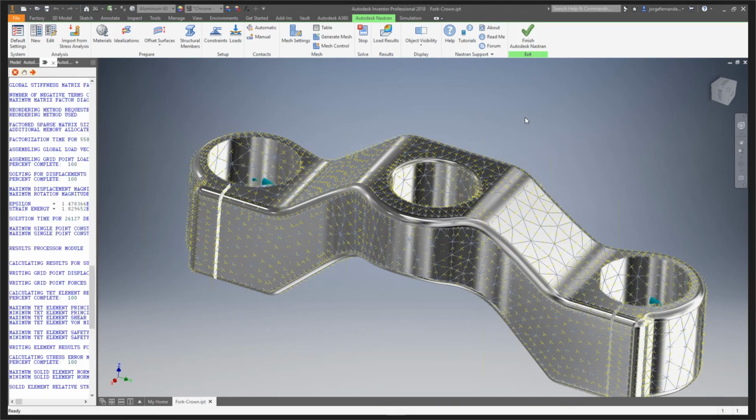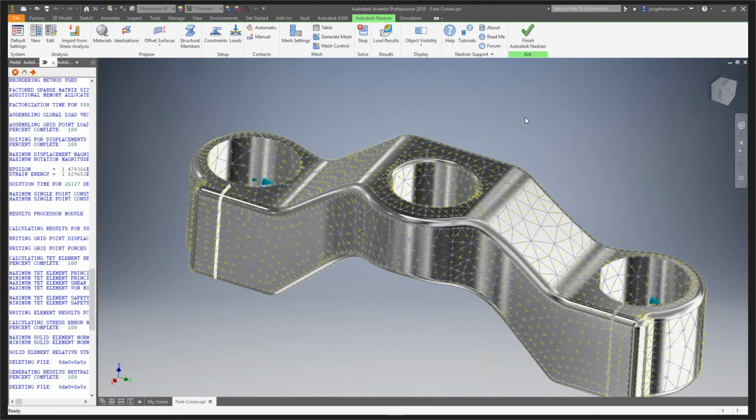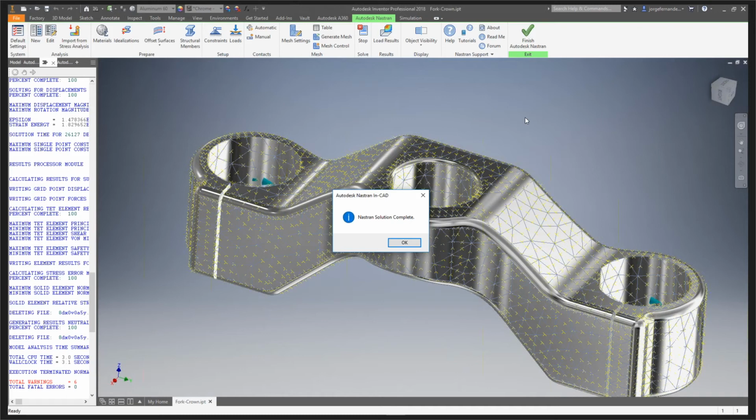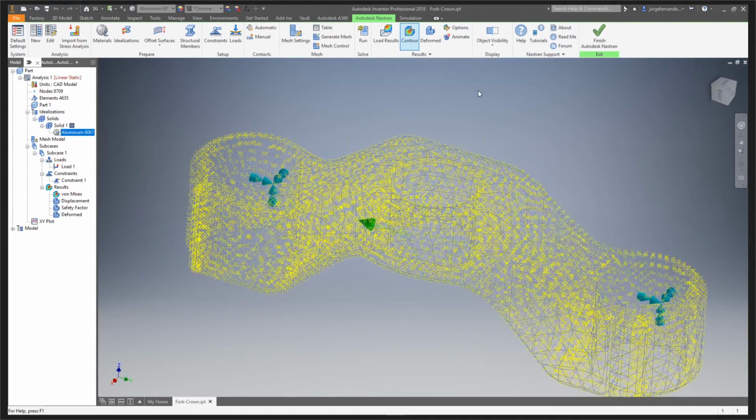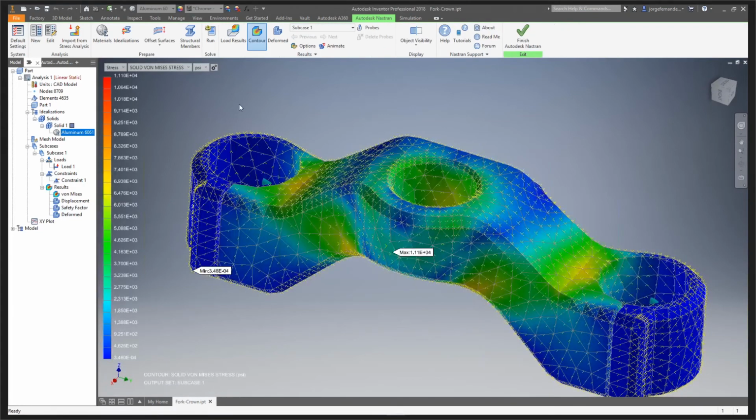So we literally looked up beforehand before we got on here. We verified again today, and the maximum yield strength was 40,000 psi. We came up with that, right, Nigel? Yeah. So knowing that, we'll take a look at the contours here and be able to decide on our own, is this part going to be okay or not? And so we go to stress, solid von Mises. We see that the maximum here is definitely under 40,000, right?